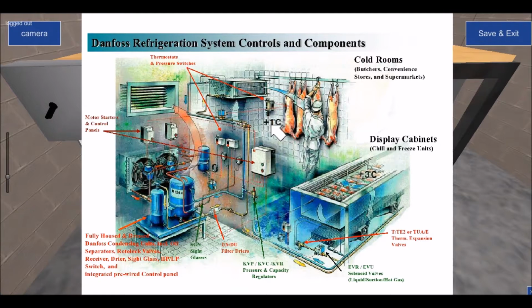So in other words, what we're trying to do is stop refrigeration from continuing once the room temperature reaches plus 1 degree Celsius. So this thermostat is measuring the room temperature, and it's set for 1 degree Celsius. So what you're being asked to do is describe how that room stat sends a signal to the compressor to ask the compressor to stop running.